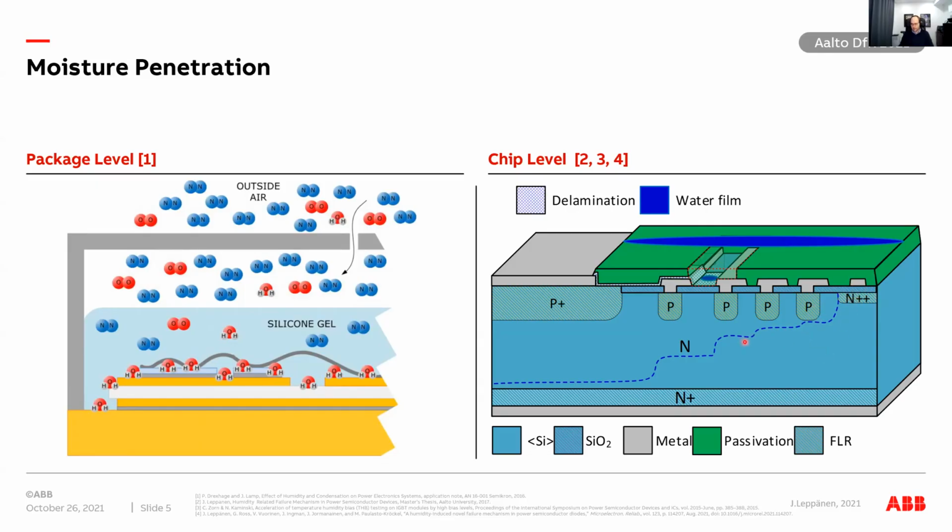So the idea is that this structure has to be there in order to terminate the electric field, because otherwise there would be exactly or almost the same potential here on the edge as here. So between this point and this point, there can be even 1700 or even 2000 volts difference, and the chip thickness is typically 100 micrometers.